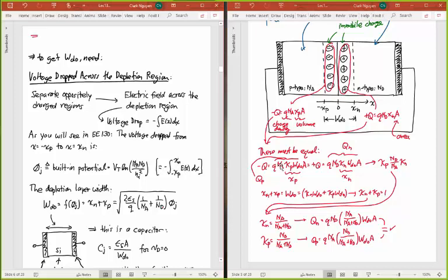But then I can also write this in a form that might be easier to remember. Because if you look at this just being equal to n sub a times n sub d over n_a plus n_d, that really is the same thing as if I wrote it using that parallel operator that we have in circuits. That's n sub a in parallel with n sub d.